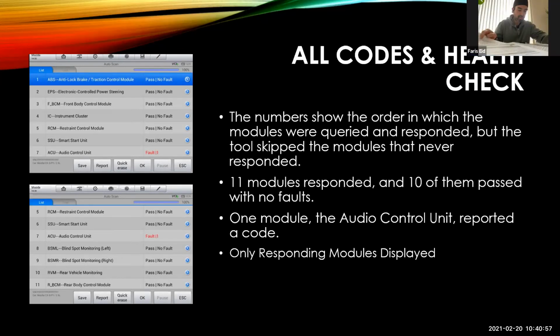And this can be a problem, because what if the module I can't talk to doesn't even show me it's there because I can't talk to it? And that's the module that controls the functions for the problem I'm having, or gets the module that is having the problem the information it needs to work properly.